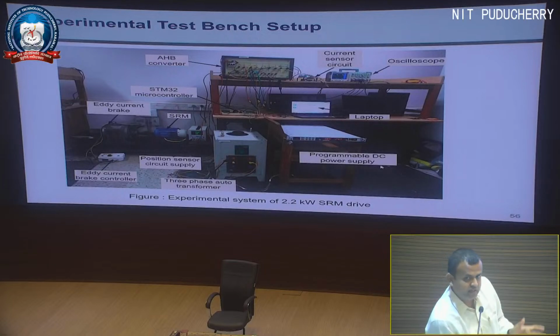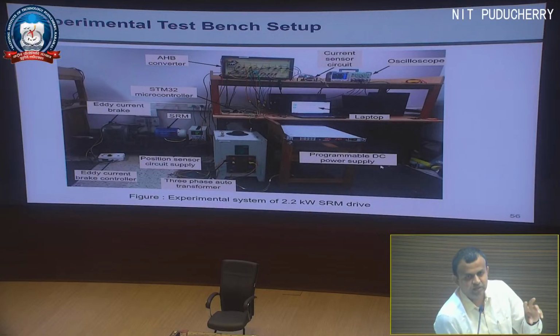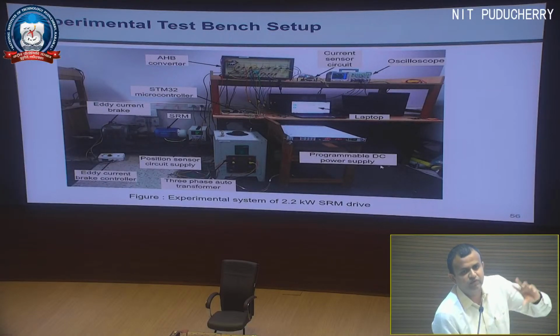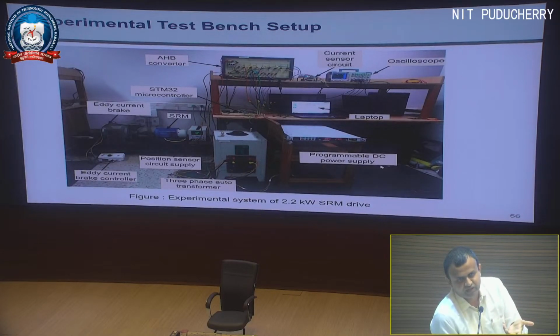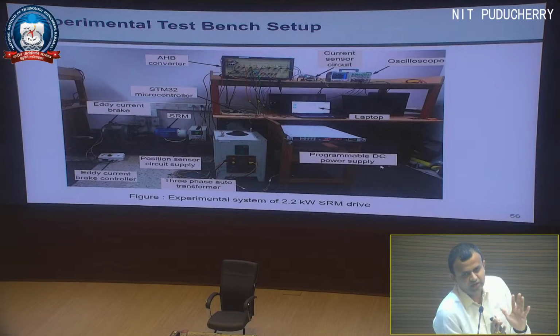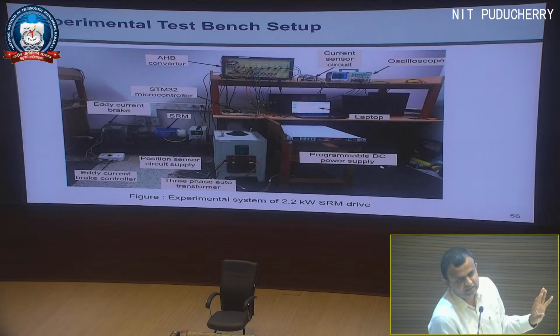And the accuracy of the torque transducer also matters, because it depends on the rotor position, right? For every how much angle it will measure the torque is also important. That will give you more accuracy. Suppose for every 7.5 or 15 degrees if it measures, then accuracy will be less. So the lesser the angle, the more the accuracy, right? It also decides the cost of the torque transducer. So we have gone according to our budget, and we have fitted a torque transducer and it is running.